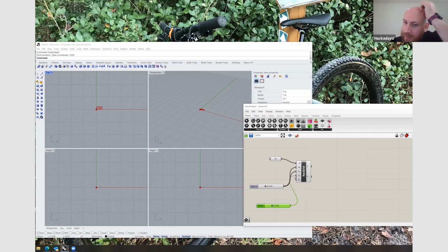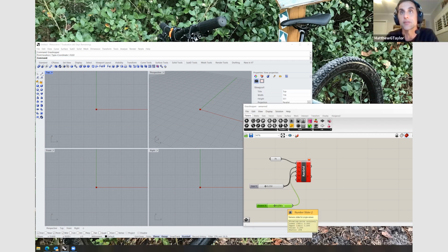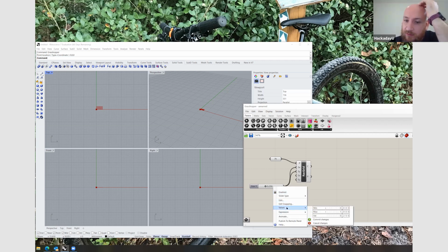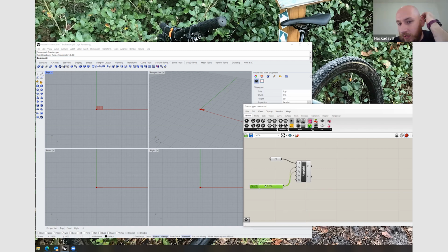So probably don't copy paste until I set my extents. Right? And you notice how it was red there? That's because you can have a floating point for the size of each of the grid cells, but you can't have a floating point for the number of cells. You can't have 0.2 cells.